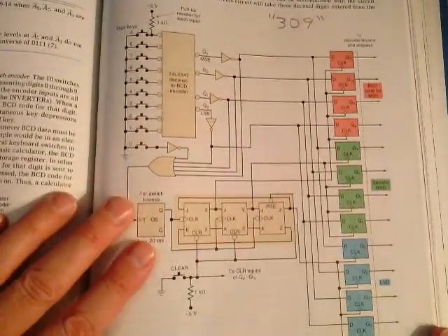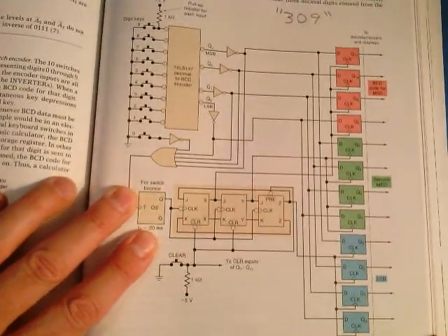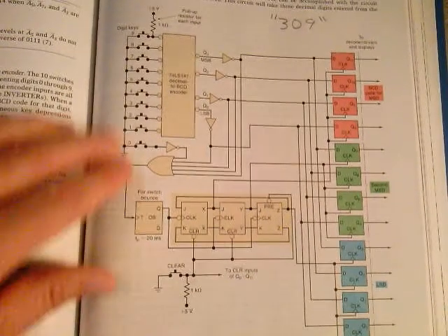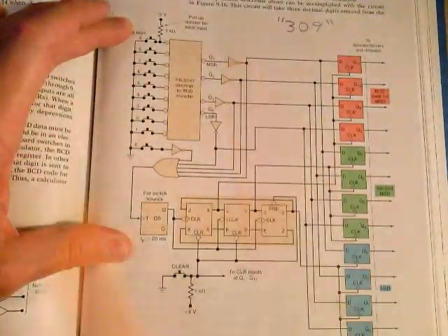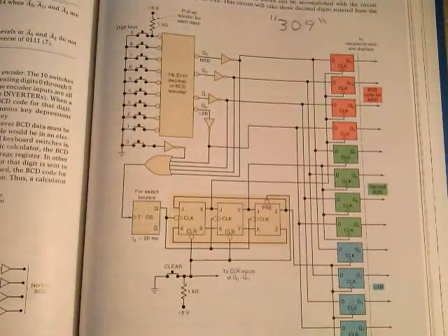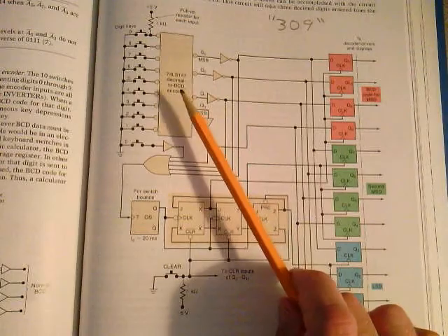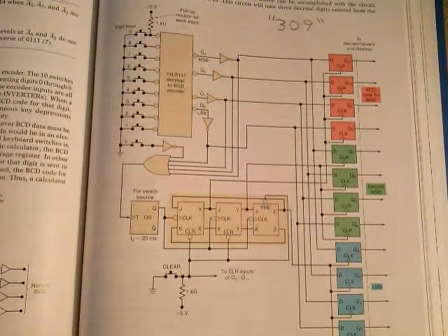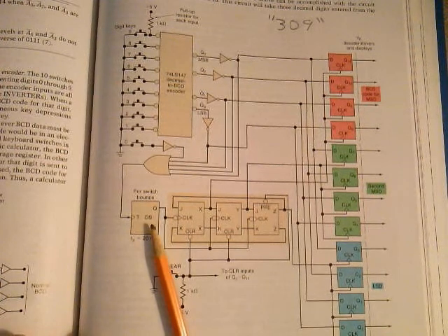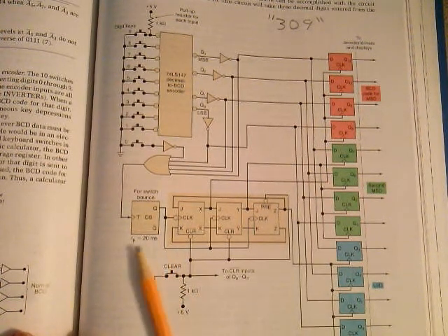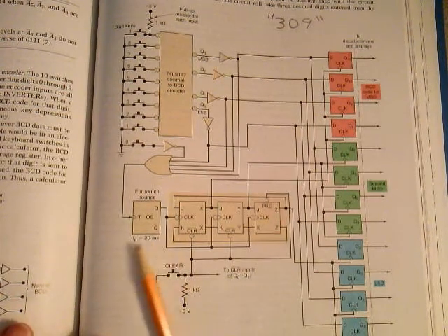I'm going to show you how this circuit works. I'm going to try to get most of it on here. We're going to put in a 309, and I wrote it here in the book so you see it. Notice this circuit right here is comprised of a decimal to BCD priority encoder. We have some logic gates here. Here's our one shot that has an unstable state of 20 milliseconds. We designed for something like that. It's pretty easy for the engineer to design this.